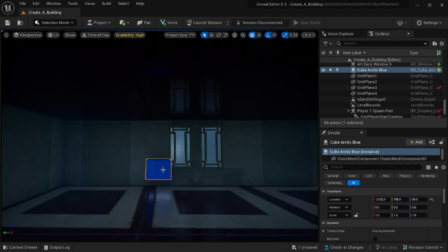With surface snapping enabled, you can move an asset using the translation gizmo, and it will automatically snap to the ground. Note that this only works if you move the asset by positioning your mouse cursor at the intersection of the 3 translation gizmo handles, where you should see a white sphere. Click and drag the sphere in the direction you wish to move the asset. If you do not position your mouse in this way, your asset can sink beneath the surface of the ground when you try to move it.